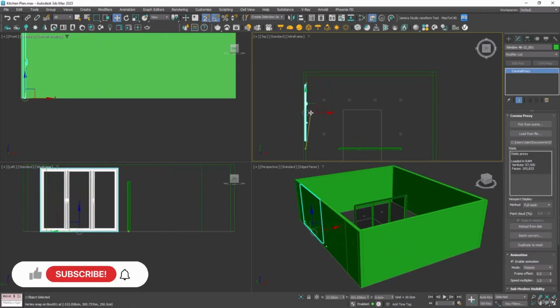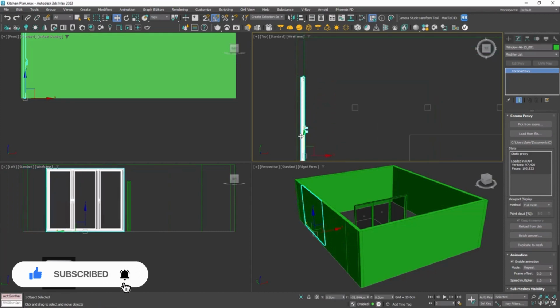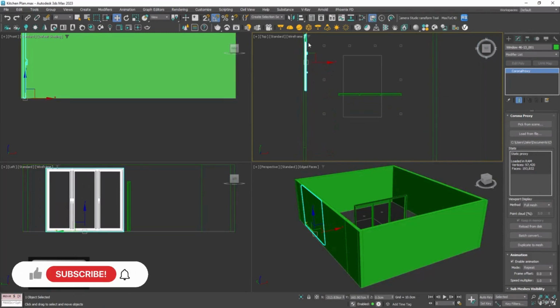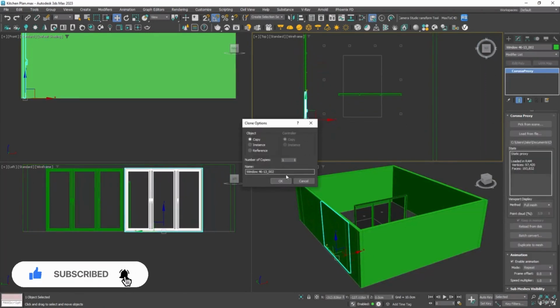And if you're ever clicking and dragging and you're struggling, you can press S to turn off the snaps to line these up. And I'm going to hold Shift and drag these down to make another copy. And we're going to make this an instance, and that means any of the changes we make to one of the doors will happen to the other.